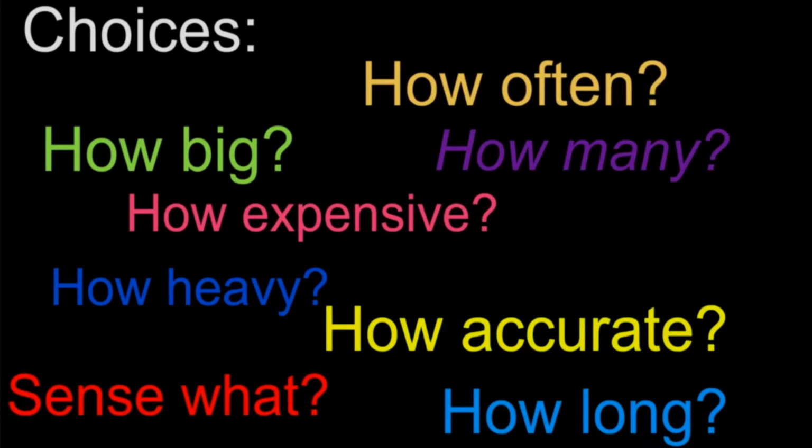to log its data. How many of these sensors do you need? How big can this sensor be, right? For example, if you're going to explore and you suspect that there might be some blockage of a pipe, then you probably want the sensor to fit through. But if you don't know how big the blockage is, how much space is left, then how big can the sensor be? How expensive can it be? How heavy can it be? How accurate should the measurements be? What are you going to sense in the first place? Is it pressure? Is it temperature? Is it location? Is it acceleration? How long does such a sensor need to be in the system? And therefore, how long should the battery last? There are many of these questions.